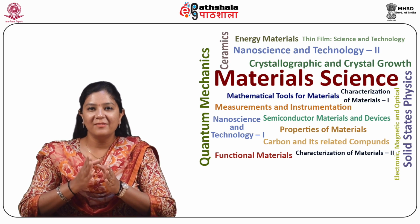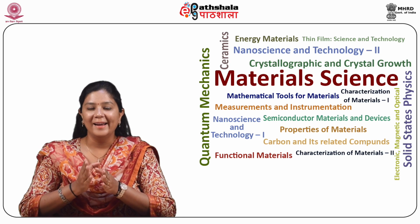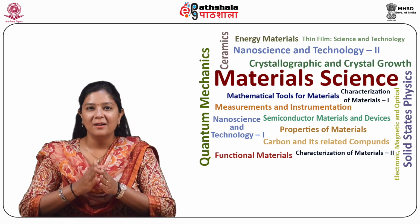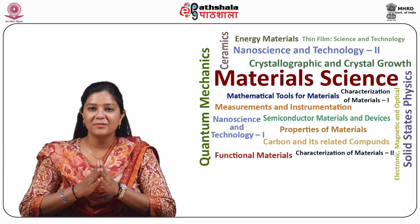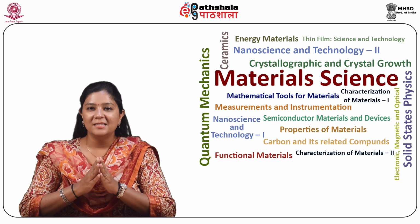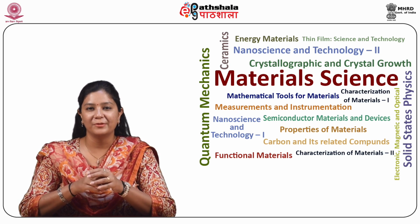So traditionally investigators have been giving maximum importance to membrane and electrocatalyst development. But as shown in the figure on cost components of a typical PEMFC stack, it becomes obvious that the commercialization of PEMFC is highly dependent on development of cheaper and efficient bipolar plates and GDL, having high conductivity and high surface area with uniform distribution of pores.